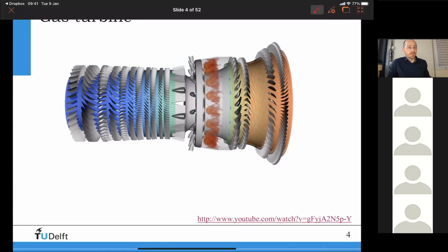You don't know beforehand how many stages you will be using for a certain pressure ratio. But if you know that one stage has a certain efficiency, then we need to apply this efficiency to each of the stages, but the overall efficiency of the whole compressor will be very different, depending on the pressure ratio and the number of stages, of course. That's why we discussed the polytropic efficiency.